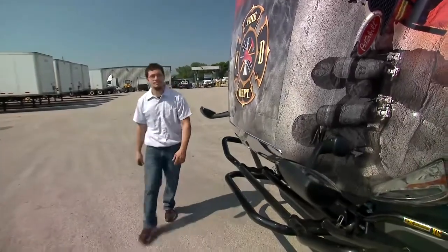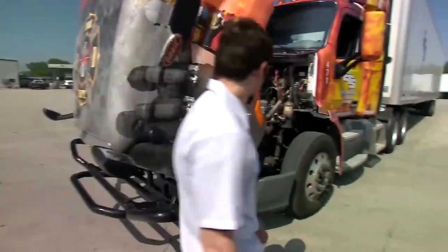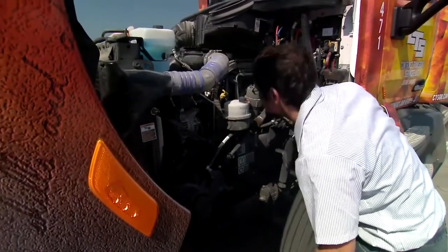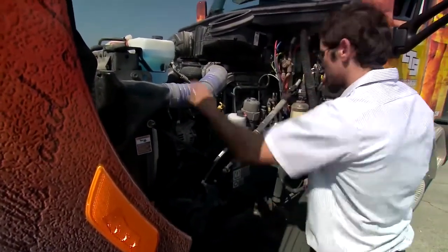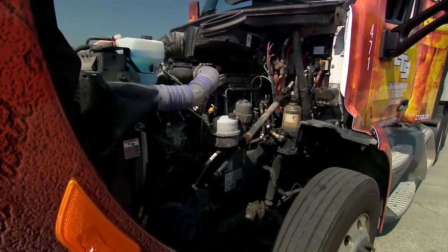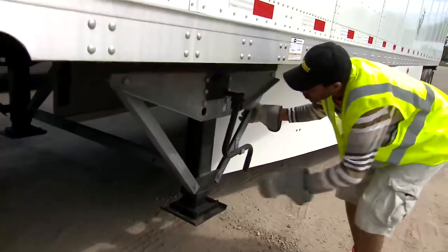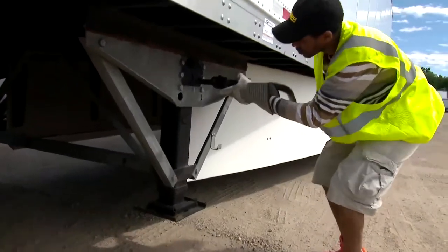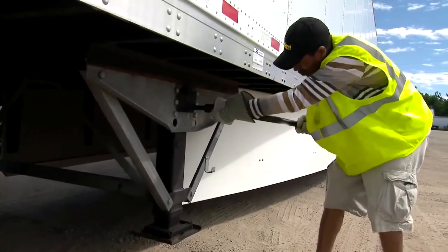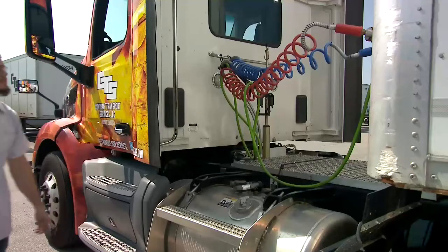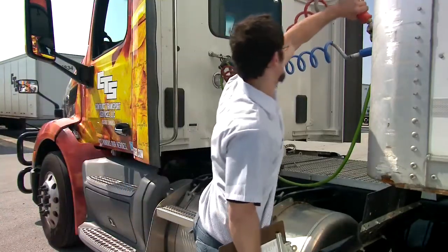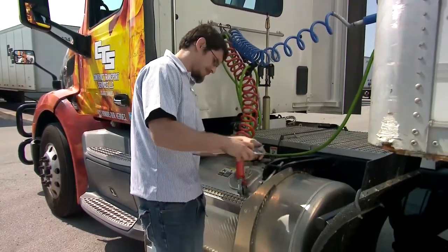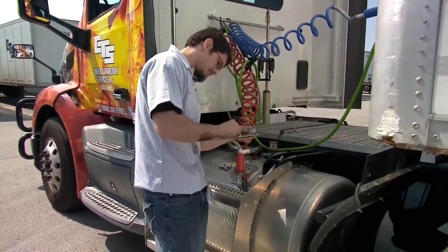During your post-trip inspection, you'll inspect the same items you did in your pre-trip. The only exception is you won't be able to check things that are affected by heat, like oil, tire pressure, brake shoes and drums, hub oil, and exhaust components. If you discover any defect or deficiency with your brakes, steering, lighting, tires, or other items that you believe might compromise the vehicle's safe operation, document it on a DVIR and report it to your company.